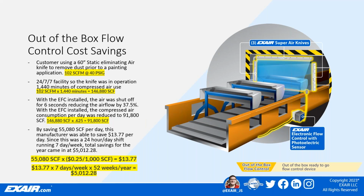With the Electronic Flow Control, or the EFC, installed, the air was shut off for 6 seconds, reducing the overall airflow by 37.5%. With the EFC installed, the compressed air consumption per day was reduced to just over 91,000 standard cubic feet. And as a rule of thumb, compressed air costs around 25 cents per 1,000 standard cubic feet of air. By saving 55,000 standard cubic feet per day, this manufacturer was able to save nearly $14 per day. Since this was a 24-hour, 7 days a week operation, the total savings for a year came to just over $5,000. This easily recouped the cost of the EFC, and it began to pay for itself in less than 6 months.